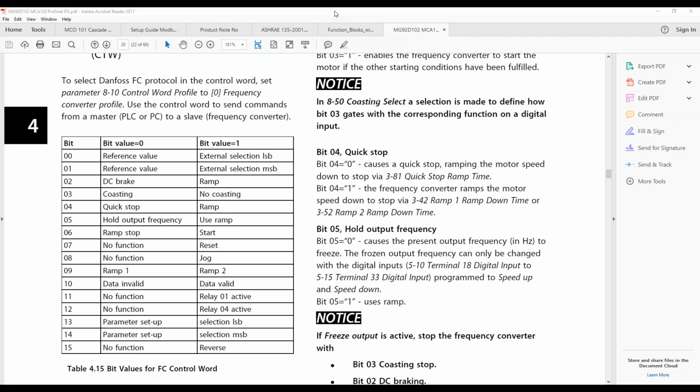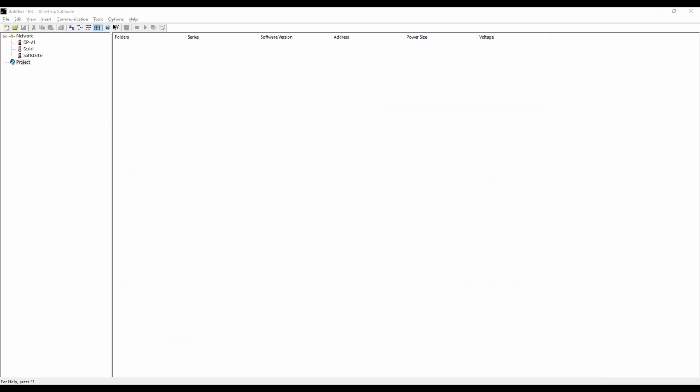Hey, Joe, could I butt in for a second and ask a stupid question? Yes. The drives themselves have coast inverse, which is the coasting function on the drive. There's no parameter you can go in and set your decel to coast like you do with a lot of drives. Well, on your coasting bit, you have a coasting option. That's letting the motor go and just using its own inertia to stop. So there is no ramp time when we talk coast.